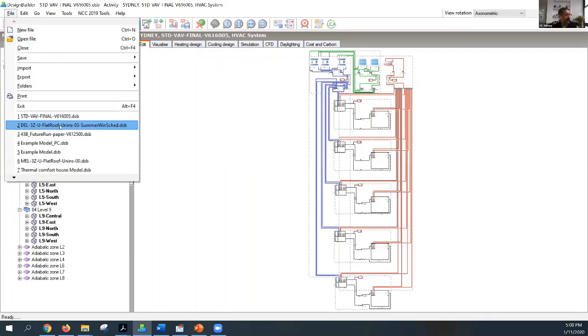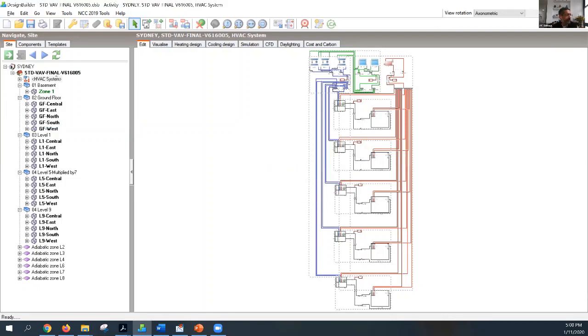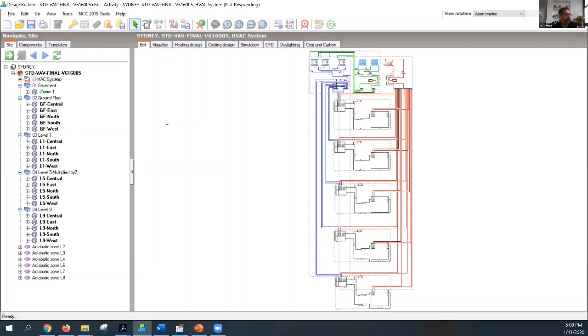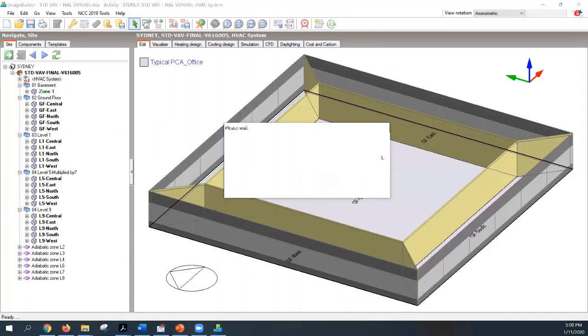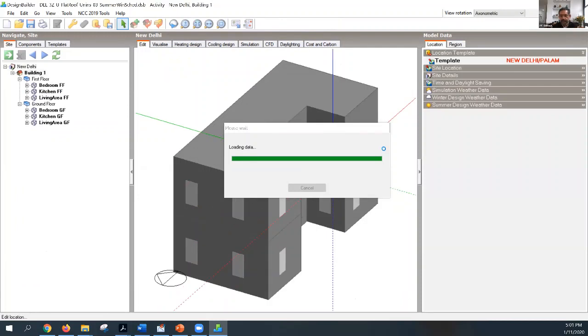Okay, so maybe I should look at that a little bit more. There is a thinking around how that works based on how mechanical engineers in different countries design systems. In Australia, we typically feel that the perimeter zone should be somewhere between 3.6 meters to 5 meters.